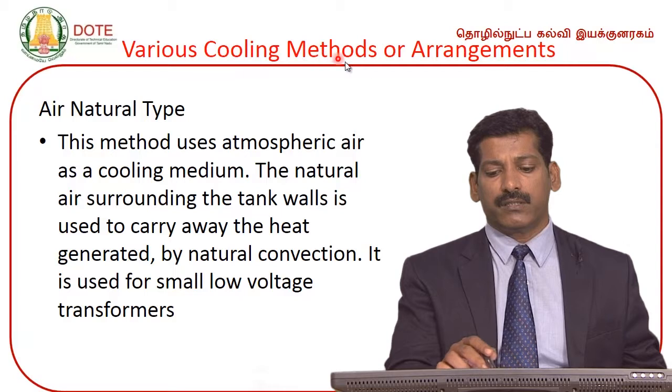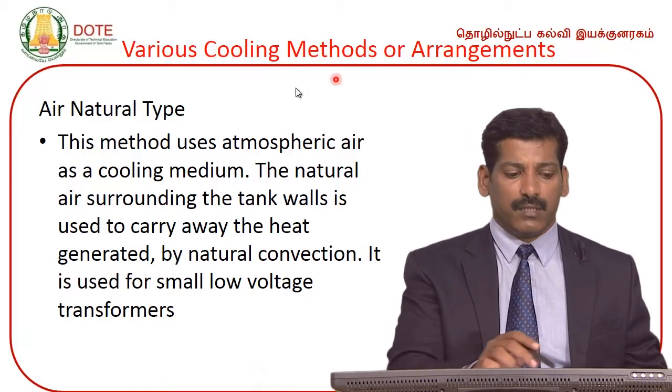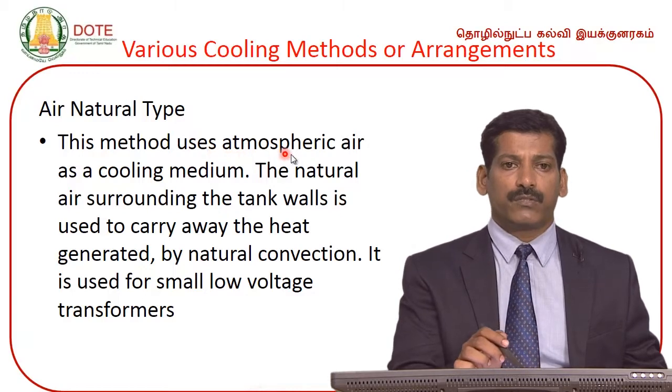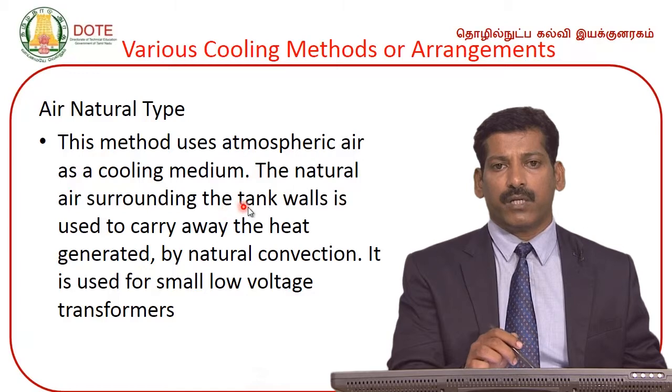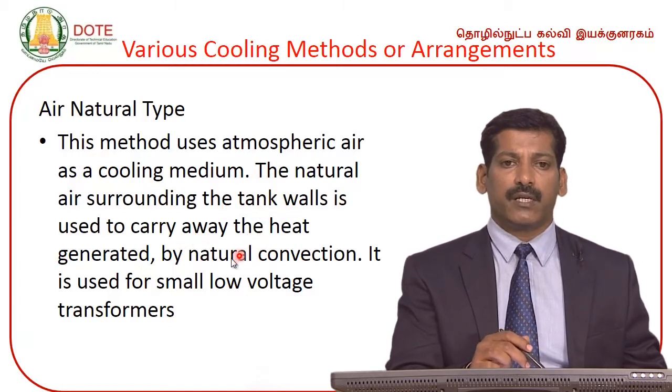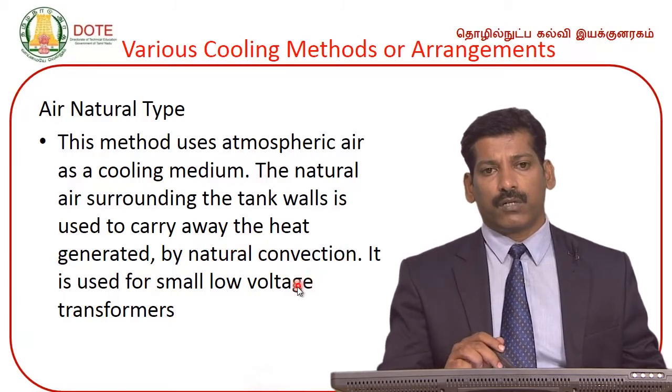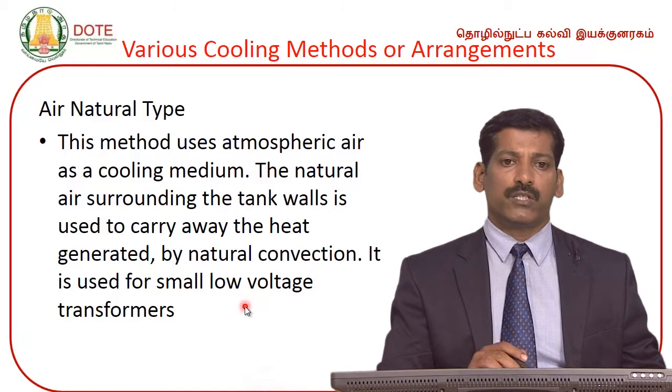Various cooling methods or arrangements. Air natural type. This method uses atmospheric air as a cooling medium. The natural air surrounding the tank walls is used to carry away the heat generated by natural convection. It is used for small low voltage transformers.